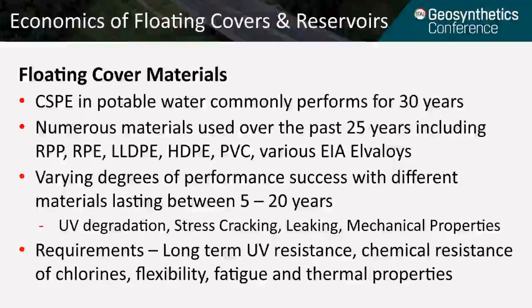There have been varying degrees of performance success with the different materials, lasting typically anywhere between 5 and 20 years. The typical failure mode has been UV degradation, premature stress cracking, leaking, or loss of mechanical properties. The requirements for a good floating cover material include long-term UV resistance, chemical resistance to chlorine and different disinfectants, very good flexibility and fatigue properties, and overall very good thermal properties, both high and low temperatures.